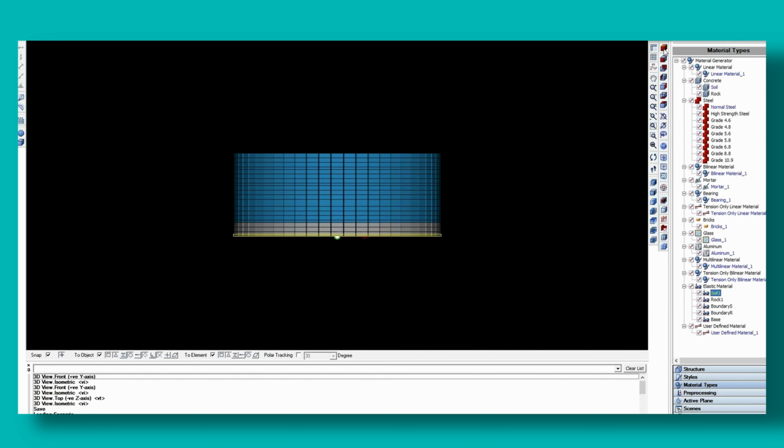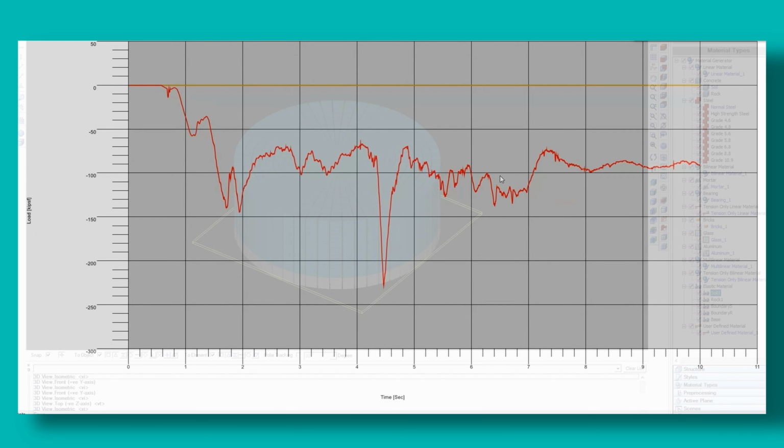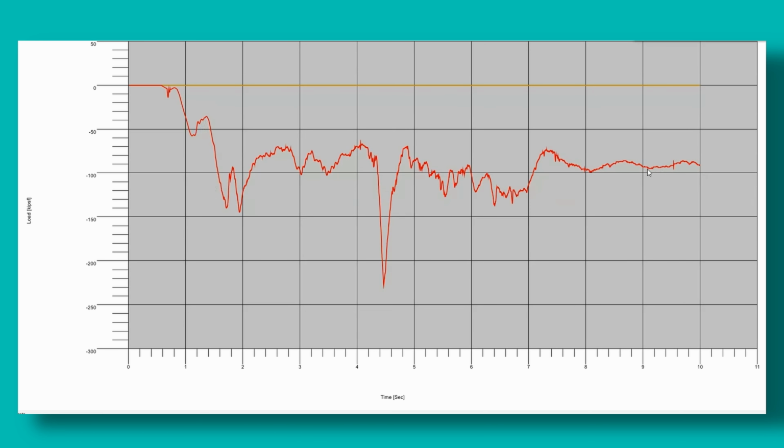This means that within about 1 second, the wave reaches the boundary, reflects back, and interferes with the input signal. As a result, any simulation lasting longer than about 1 second becomes distorted by artificial reflections, because in reality, the soil extends to infinite distance.